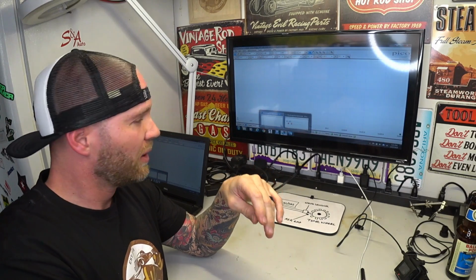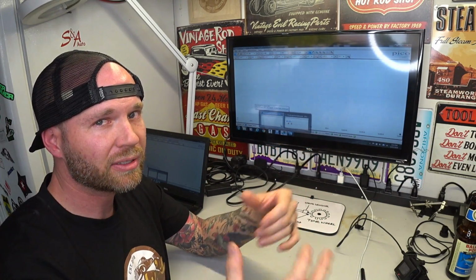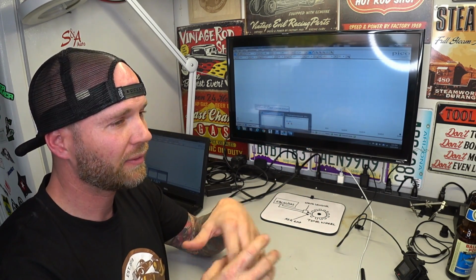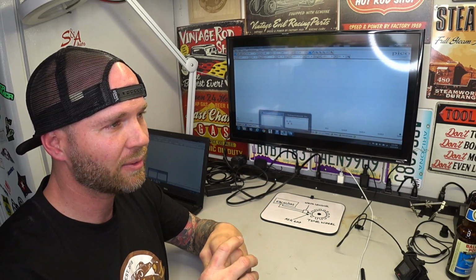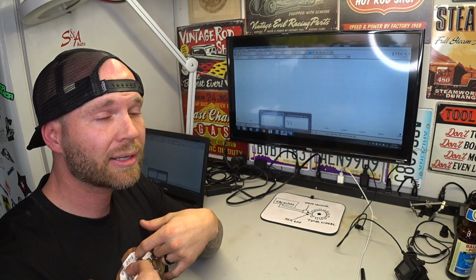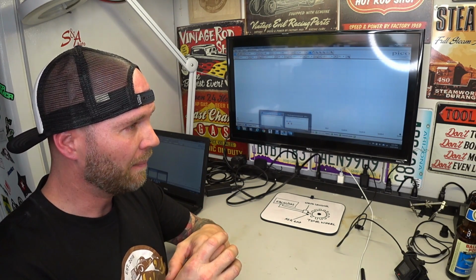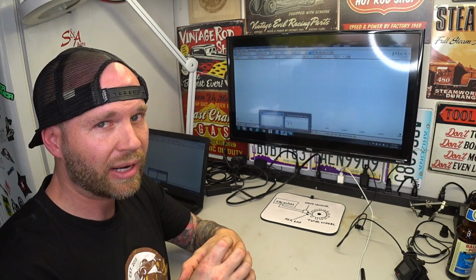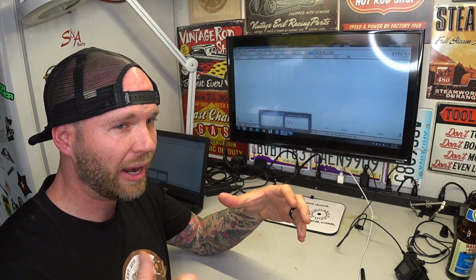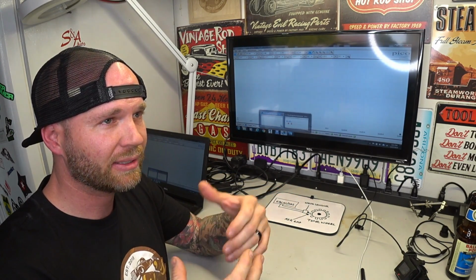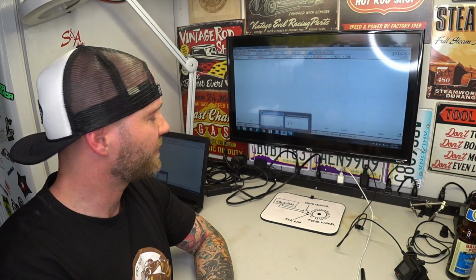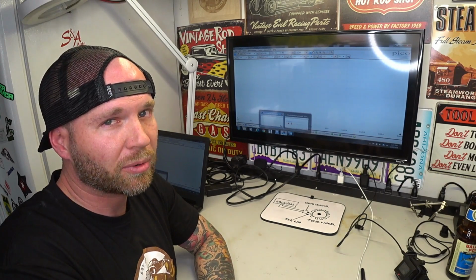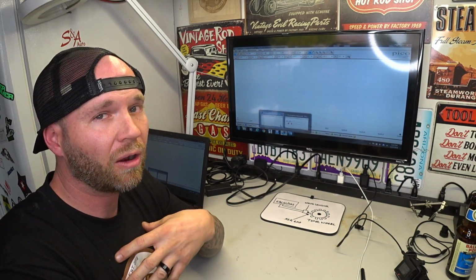So I showed you guys the rotor, the low spots and everything on it. So the fix for this was replacing the right front rotor, free of charge to the customer. It's under warranty. I didn't see any hammer marks on it. I didn't see where it was a defect on our end installing it. These rotors come with the races already installed, so it's not like you're hammering in races. The only thing you're doing is tapping in the seals, the grease seals a little bit. You're not even hammering on it super hard. So I didn't see a defect on our end.